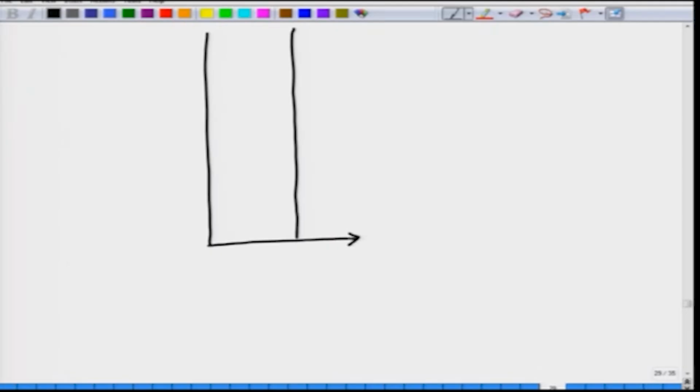So, on this horizontal axis, Z equal to 0 obviously corresponds to the source, and Z equal to L would correspond to the load. Along here you can also write the value of gamma S. I suggest that you write this so that you always remember the values of gamma S and gamma L, instead of all the time going back to some page and looking at the values out there. Writing this will also help you do a sanity check on your lattice diagrams, because you can very easily figure out where you have made a mistake.